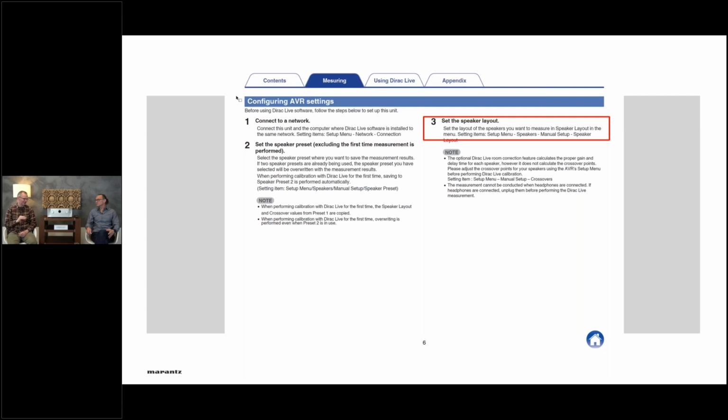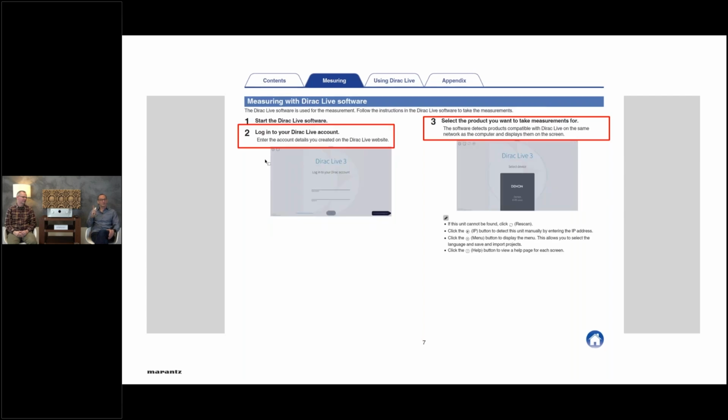You don't have to forget it, but if you set it after this, from the measurements you get an idea where to set this crossover frequency. Okay, that may be helpful information here. So if you understand how to read the frequency response of the speaker, you can identify where to put the crossover setting best. Okay. But don't forget to set it.